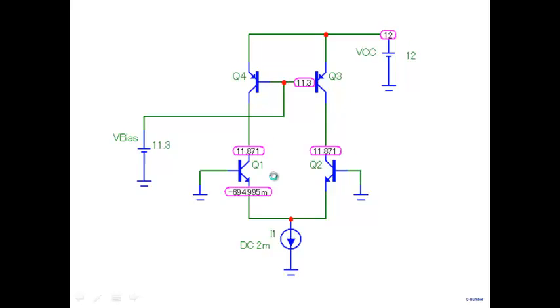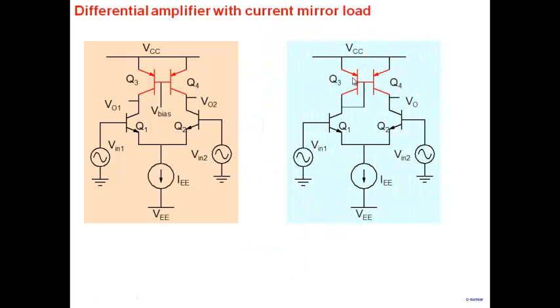Go back and see what we have obtained: two identical transistors, where one transistor's base and collector are shorted together. So biasing is an issue, and as a solution, if you take this point and just connect it here, just one simple connection will solve lots of problems. Note that I no longer have to apply a bias voltage. There's no bias voltage required now. But do you see a problem?